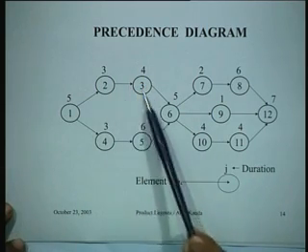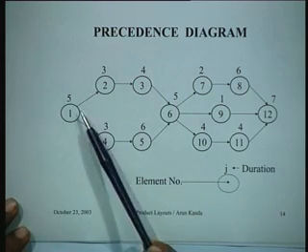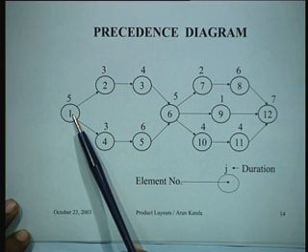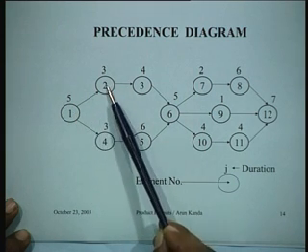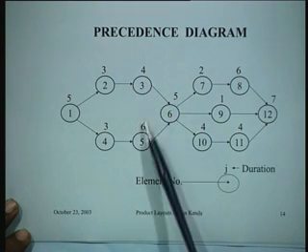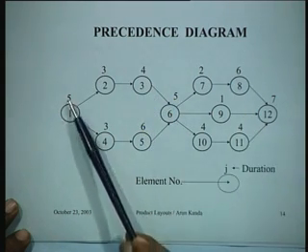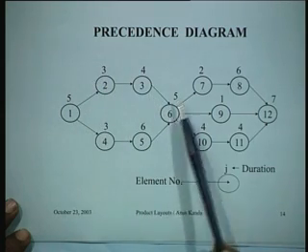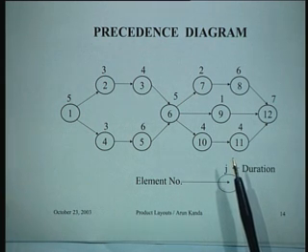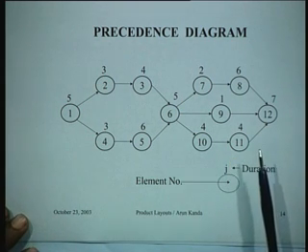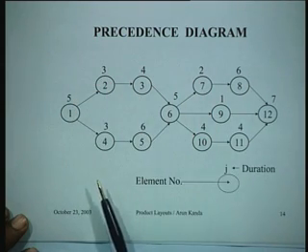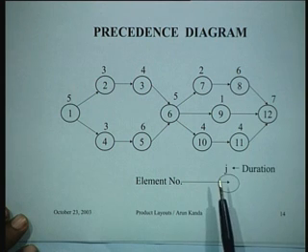So we have divided the entire task into these 12 operations, and this network diagram shows the precedence requirements. That is, operation 1 has to be performed first, and then 2 and 4 can be performed. Similarly, 6 can be performed only when 3 and 5 are over. And the figures here refer to the duration of each task. The duration of the task would be determined by a time study or whatever other procedures you have. So you know the times required to do these individual tasks. From this we would like to possibly design an assembly line.